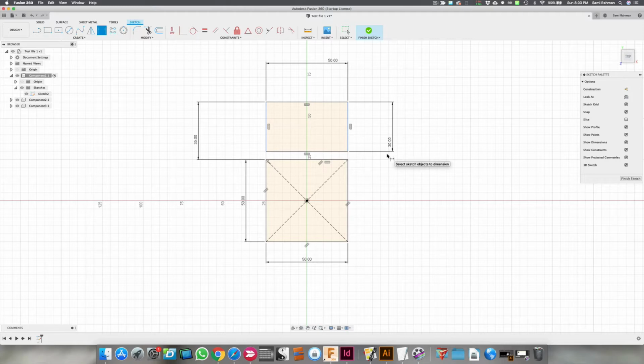30. Boom. It anchored from up here because that's where I started the drawing. So that was my anchor point, and when I changed it, it moved the drawing. There's a whole sort of language to how all this stuff moves. But it's very interesting. What you click on, you may not know. You need to be very precise about what you click on. Otherwise, if I wanted this to be 35 and I typed in the wrong spot, look how it's not 35 anymore.